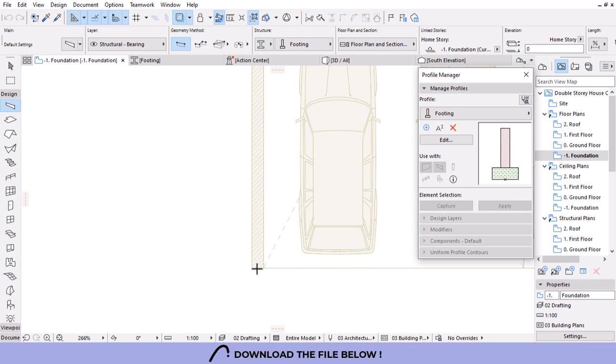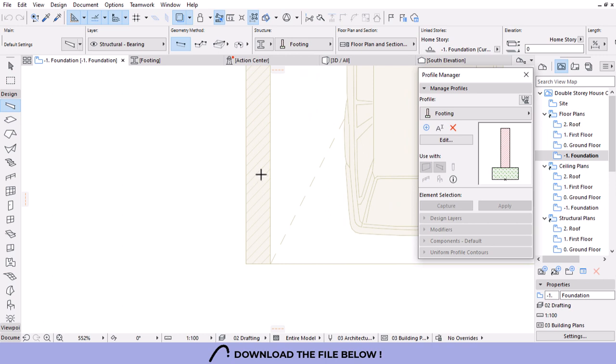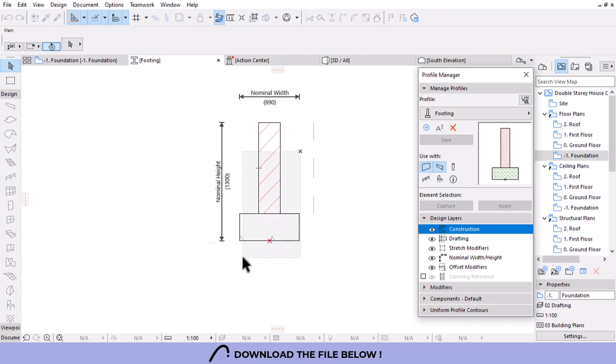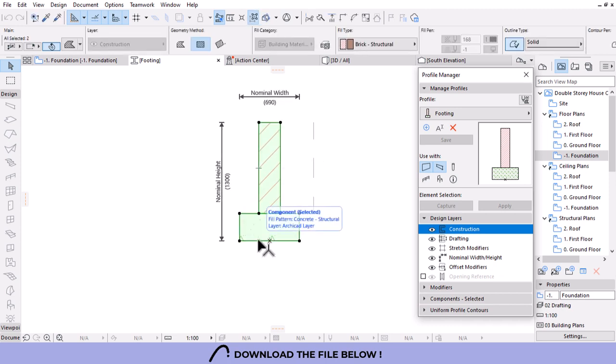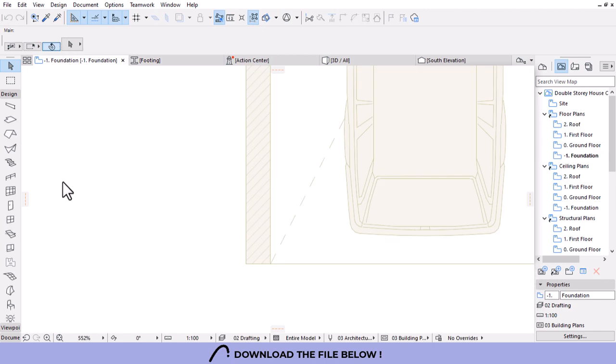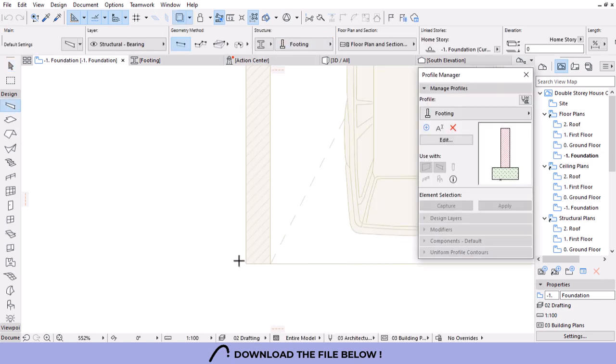So you see, I've made a mistake by using a reference point for the center or the x-axis. So now it's placing, and if I draw it, it's going to be outside. As you can see, it's not correctly done. So what I'll do is edit this, and then use the edge of the brickwork, which is this point, move it to there, and hit save. Go back. Now if you activate that, you can see it's correctly placed.